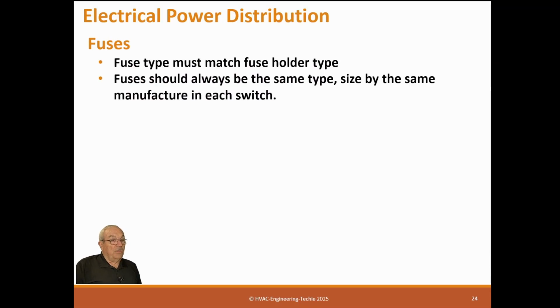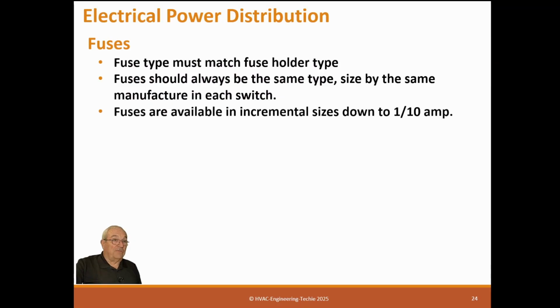So basically we want the fuses to all be the same, hopefully all the same age. So when you replace one fuse, you really should replace all three fuses, unless you keep them in stock, exactly the same brand. That's kind of important. And of course, there never should be anything else in a fuse holder. Can't tell you how many times I've seen a piece of copper pipe in a ferrule holder. Oh, it works fine, but it don't protect anything. That's the problem. So it needs to be what it's designed for.